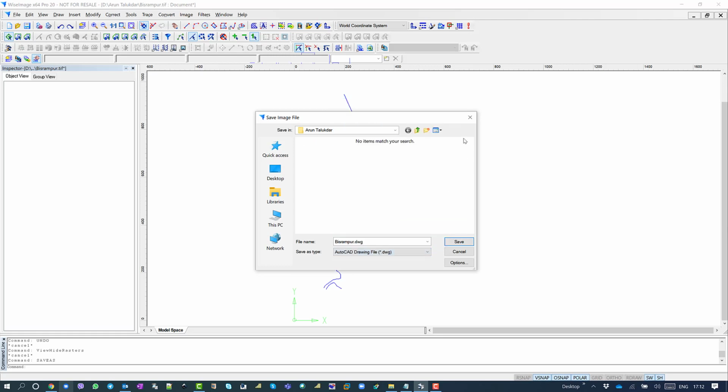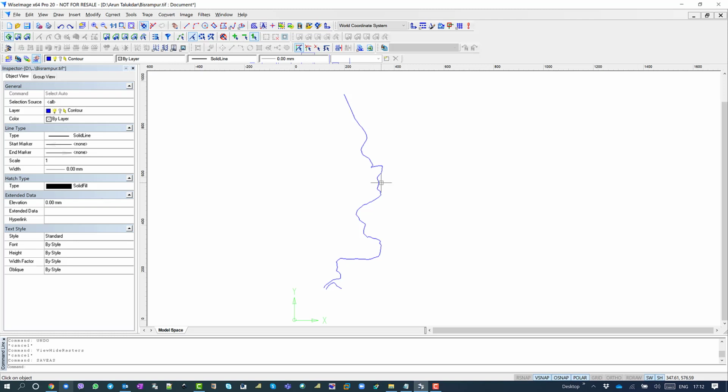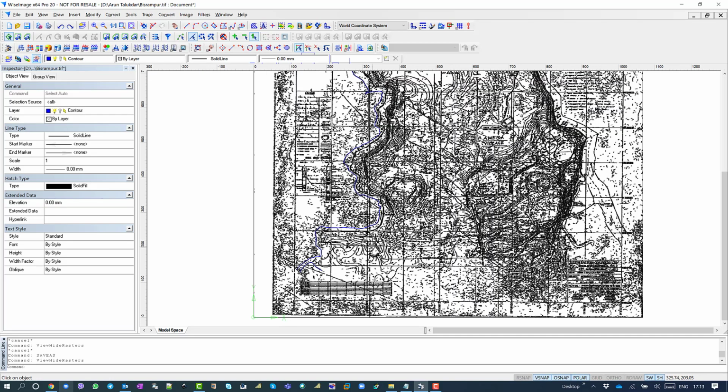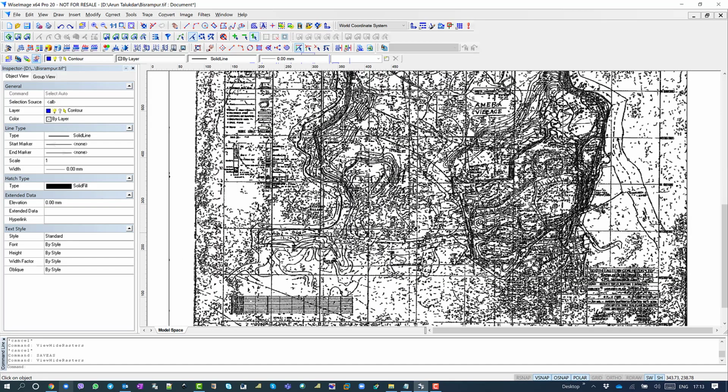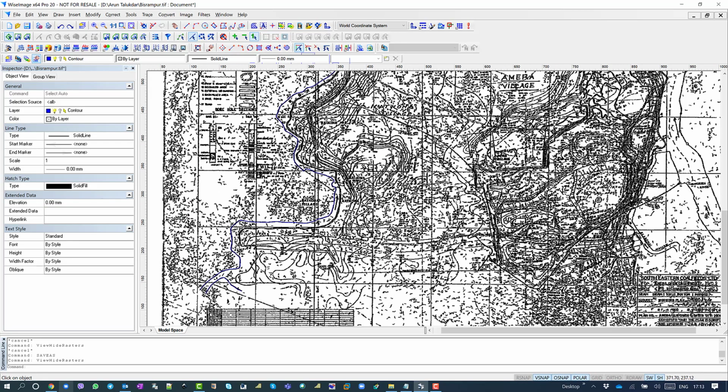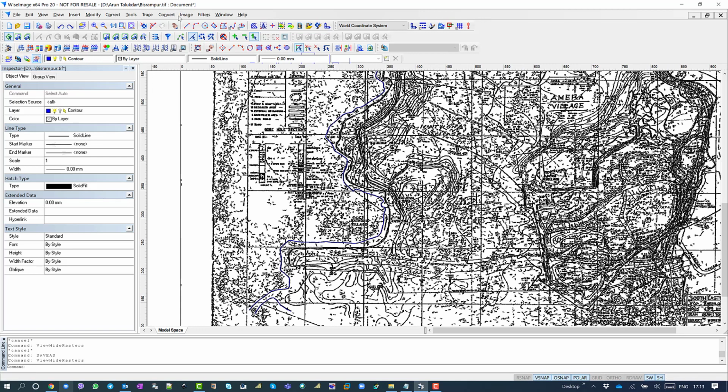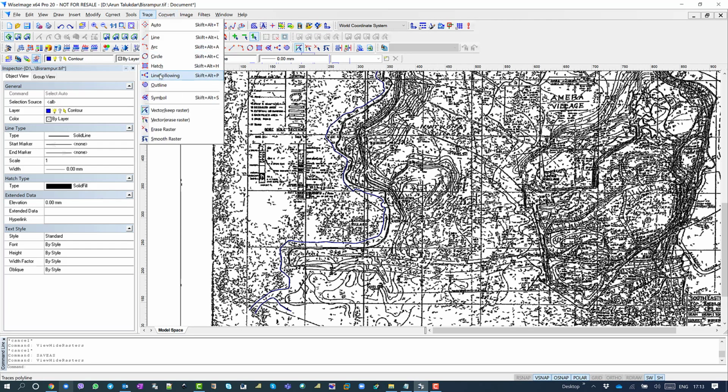And one more thing, maybe you require it, you can create a sort of surface to see. If you convert this into a vector contour, then you will have options to visualize the surface, how the contour surface will generate. So WiseImage has those functions. But for now, in this video, we are talking about how to use semi-automatic tools like line following for complicated contour drawings. So maybe this is the solution.